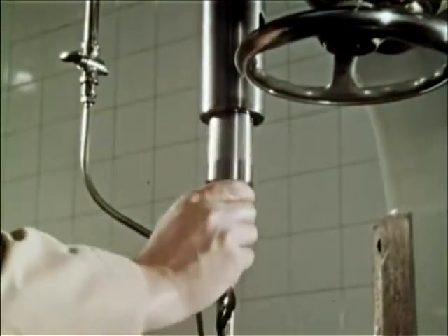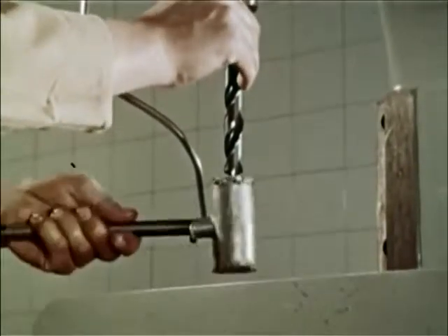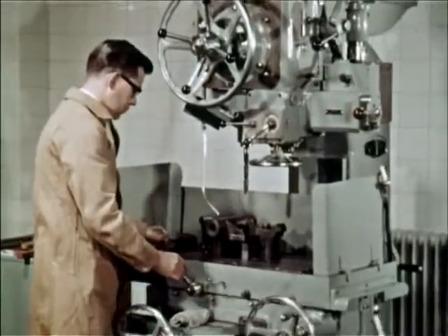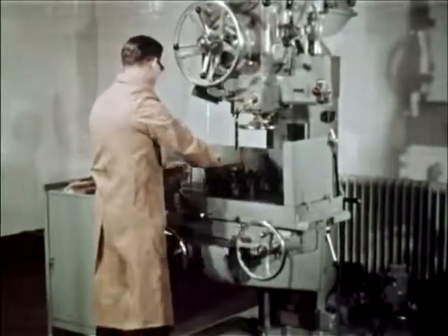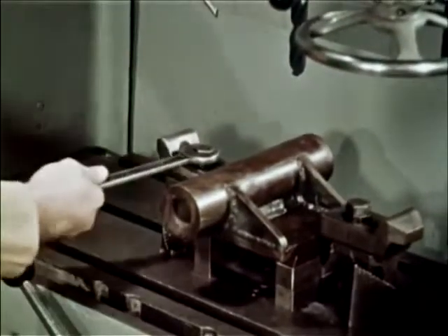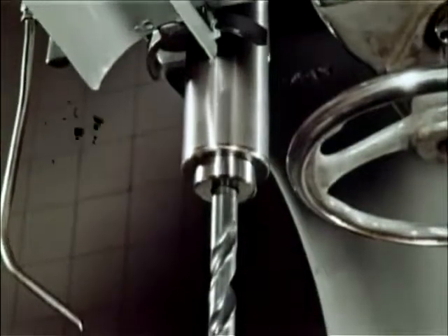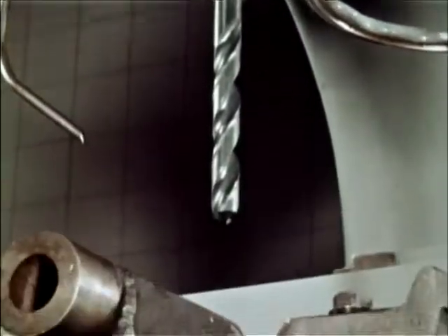Don't ruin the drill before you even start work by using steel hammers or spanners. A mallet of wood or some other soft material such as lead should be used. Make sure that the workpiece you're going to drill is rigidly held. If it bends or moves in any way, a strain is put on the drill which will reduce its efficiency and possibly break it. Reduce the quill extension to the minimum.